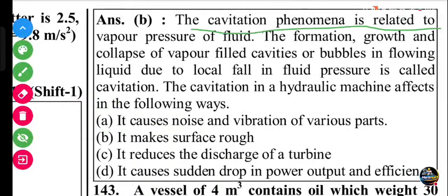The cavitation phenomenon is related to the vapor pressure of the fluid. The formation, growth and the collapse of the vapor cavities or bubbles in the flowing liquid, due to the local fall in the fluid pressure, is called cavitation.